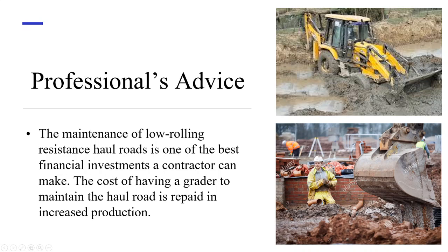You think you're saving money, but in fact you're not, because many equipments are passing over the construction site surfaces tons of times, right? So if there is higher rolling resistance on the road, the result is less productivity, less speed, and this means more money. So it pays off to spend some money on maintaining the surface condition.